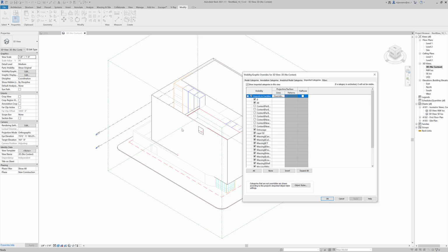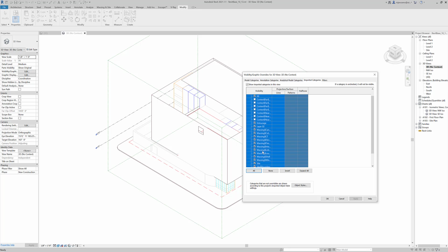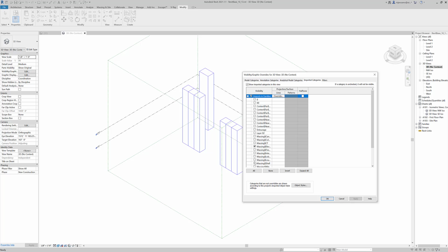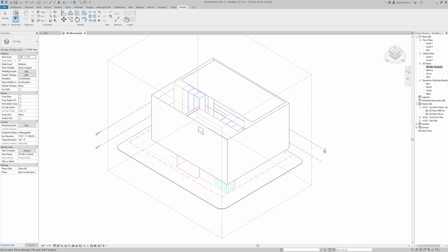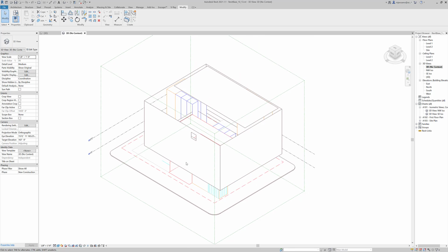If in some instance you need to model something on the interior and you just want that face, and you really need that face because it's curved, you can go to All, and then you can Control click, say, the elevators, and also Control click the imports and families, the parent family, and then uncheck it. And then you can hit Apply, and so now you can see that those are all my elevators. So I'll hit OK here, and I'll do Control Z so you can see it.